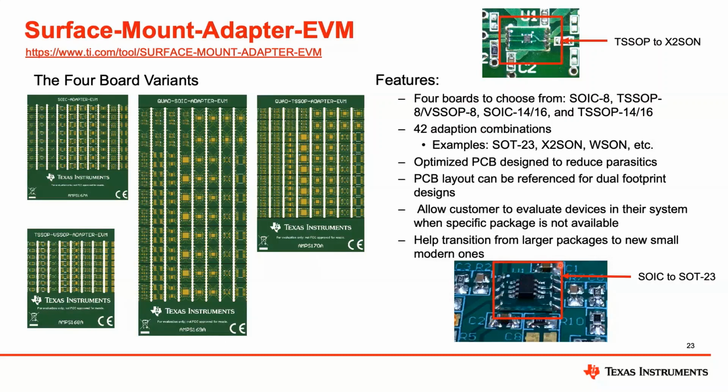Yeah, and I also just want to add, this allows, let's say we're out of one of the devices on TI.com, we're out of stock on an SOIC package, a dual SOIC, but we have a DDF package or another alternative package. The customer says, well, you don't have the package, I can't evaluate your part in my board. Now you can with the adapter board. You can put this directly on a customer footprint with our smaller package, and the customer can start evaluating it in their system, which is a super powerful and helpful tool to get designed in.